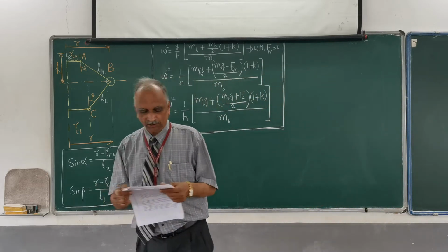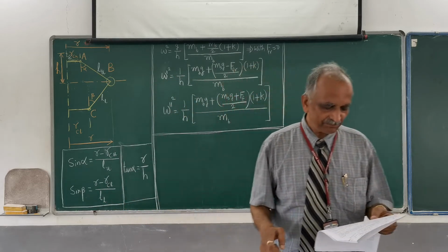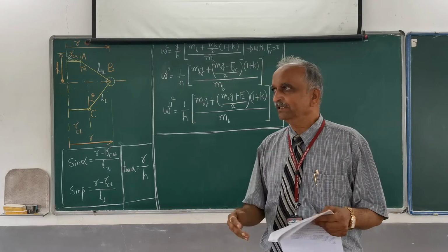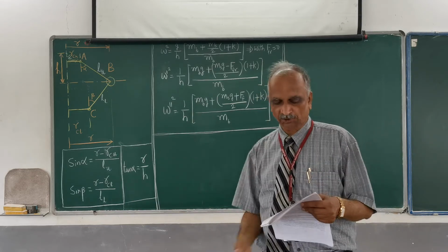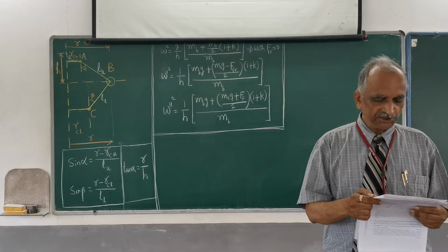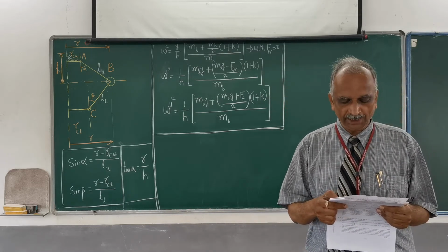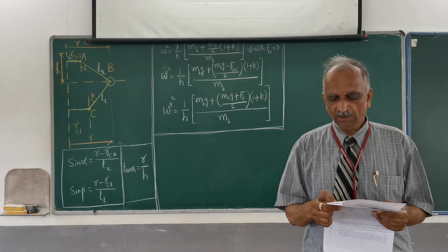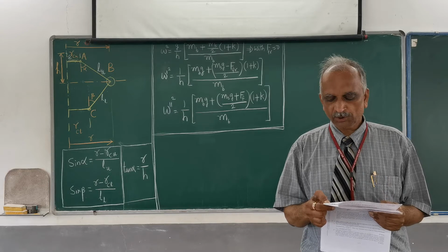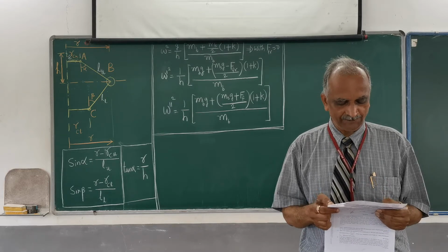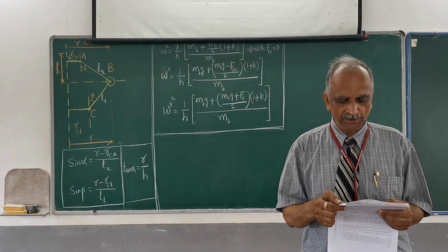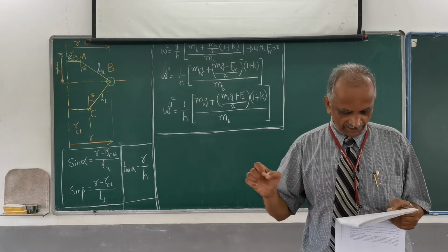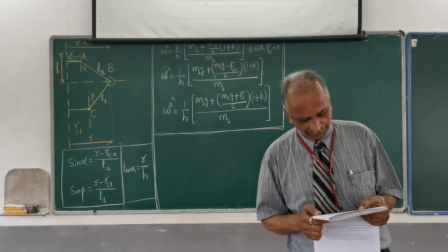Okay? So the problem goes like this. First I shall read, and then I shall come back and read it again, and in the second reading I shall also write down what are the given things. In an engine governor of the port type, the upper arms and lower arms are 200 mm and 250 mm respectively, and pivoted on the axis of rotation. So please, while reading itself, you try to understand what is the meaning.